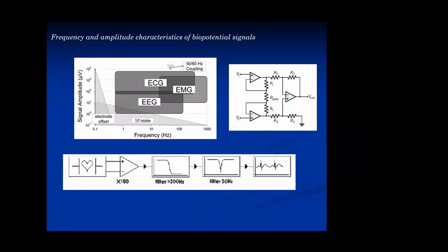Basically, in analog signal processing, the signal coming out of the electrode has to be isolated from the patient by means of an isolation amplifier, and you have to provide high gain, high CMRR and high input impedance by means of an instrumentation amplifier. And you have to reject the noises beyond 300 hertz, because below 300 hertz there may be some useful frequencies of ECG.